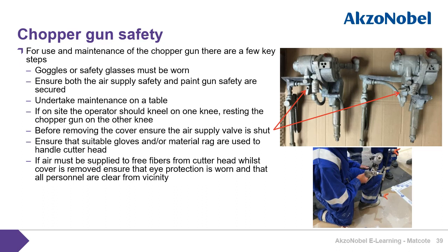Before removing the cover from the chopper gun, ensure the air supply valve is shut. If you see the picture on the right, one gun has the air valve open and the other one shut.